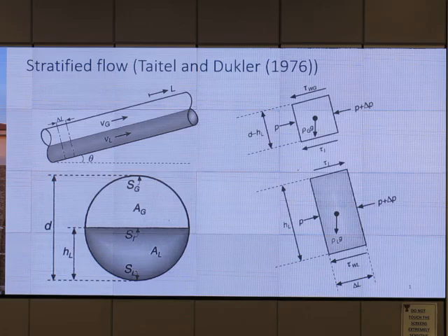When we do a force balance like this, it is only for time average. If you do the measurement, you get values that fluctuate up and down. It may not be because of the meter. It may be because the flow itself acts like that. And the equation that we have is for time average parameters, not for the value at that point in time. Make sense to you? Okay.